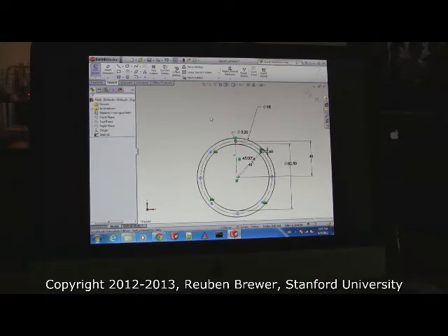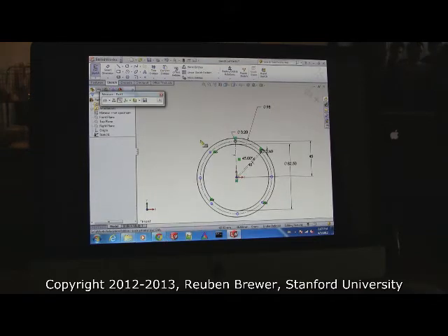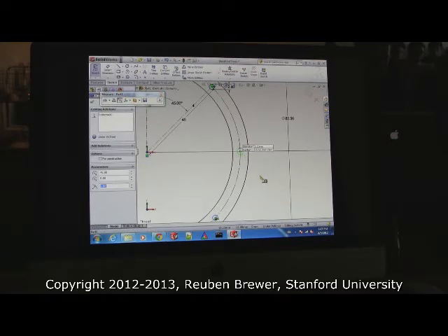So go up to Tools, and then Measure. Now your icon looks like, well, to me it looks like a razor blade, but I know it's meant to be a ruler. And now click on one of the blue holes, and it shows the diameter is 3.2. Now click somewhere off the screen, and click on a different hole, and it's 2.6. This is the second most useful thing in all of SolidWorks, the little ruler thing. That's how you sanity check everything.